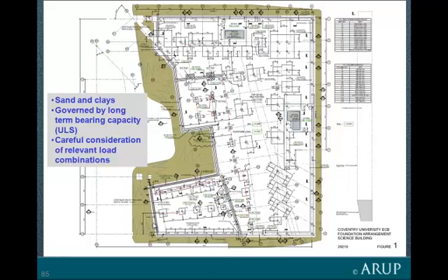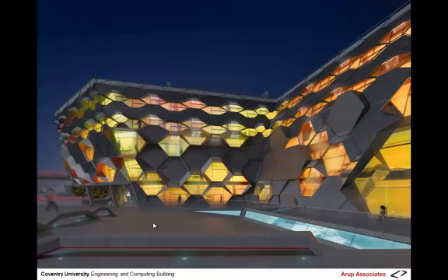What you do find for structural design is that a very careful consideration of all the relevant load combinations is necessary, because the structural designers are being taken through, in the Eurocodes, load combinations quite carefully. They have to be clear about them, and it's very important to get good communication between the foundation designer and the structural designer to make sure who's applying the factors and where, particularly the partial factors. Are the loads coming from the structure factored loads, or are they not? But that building is under construction and I think will look very nice.